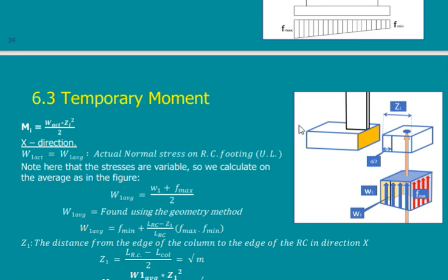They will continue phi 22. So I will not calculate this because I don't need it. But I may calculate the perpendicular direction because there is another set of reinforcement in the perpendicular direction. There I will check which is the critical cantilever, and in my case, because I have moment in one direction, in the other direction both cantilevers are of the same length. Anyway, we'll concentrate now on this direction.